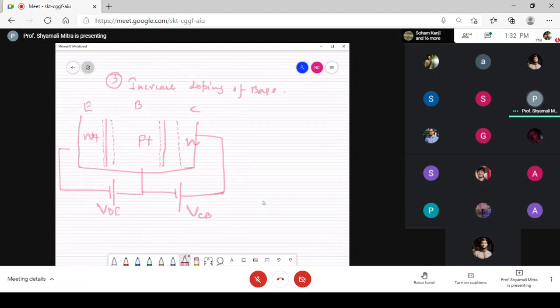Now, some of the voltage drop will be across the series resistance. You must have noted that with the increase in depletion region width, there is one resistance associated with it. We have drawn this in the context of when we tried to derive the increase in resistance when we are reverse biasing the PN junction diode.